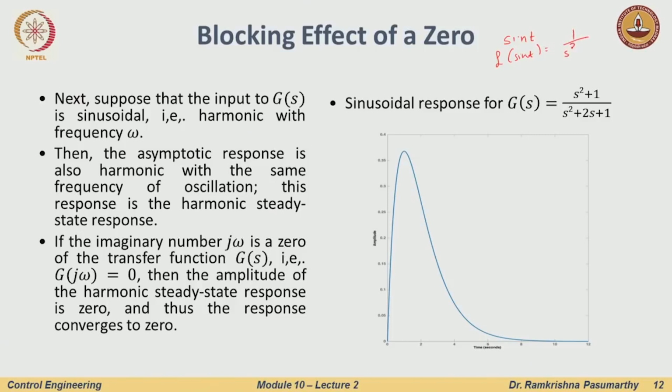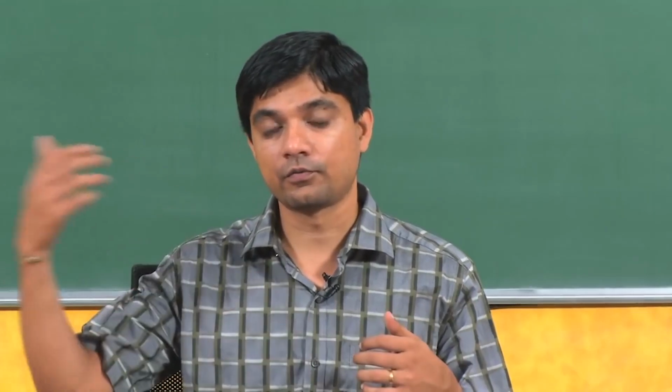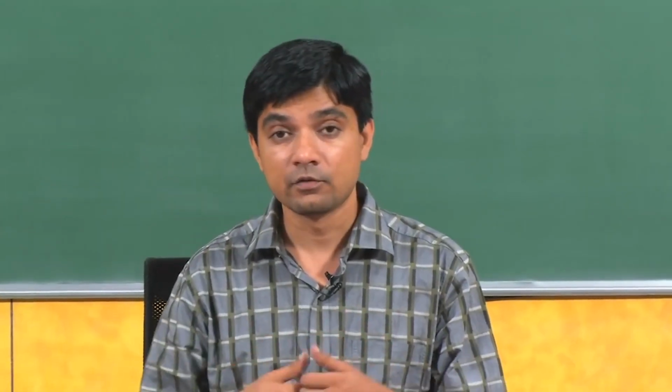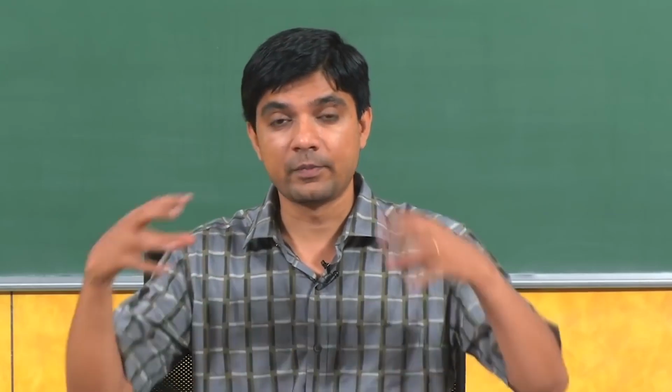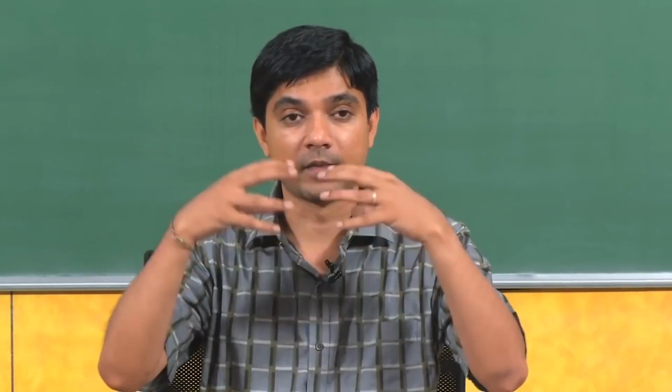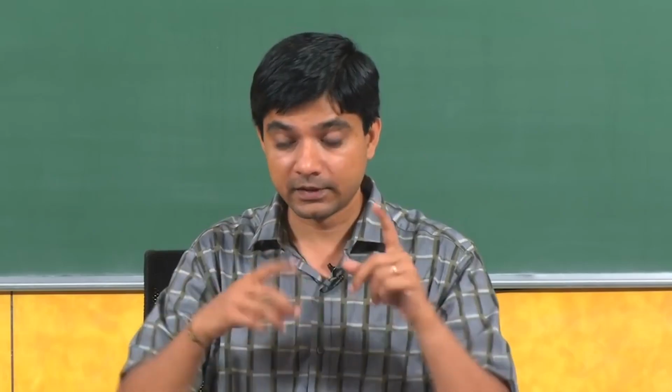which has a Laplace transform of 1 over s square plus 1, then typically what we had learnt earlier is that if the input is a sinusoidal signal, the output for a linear time invariant system will also be a sinusoidal signal. What will change? The magnitude will change, the frequency will remain the same, and there might be a bit of phase shift depending on the components sitting in my plant or process. But that is not always true.